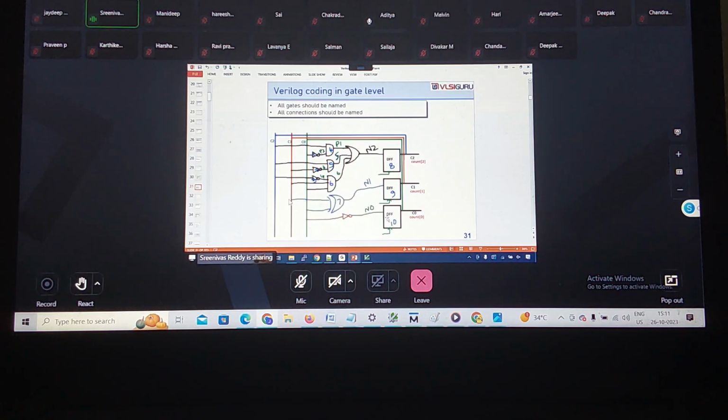That is where the concept of simulation comes in. So what I do as part of the simulation is, I will take this circuit and develop Verilog code using this behavior. Going forward, this kind of model coding is called the structural modeling style. I'll explain today itself what exactly structural modeling is. In structural modeling, we develop code which is similar to this circuit. Then once you have developed the code, how do you prove that the code is actually working? We run the simulation. To run the simulation, we apply inputs.